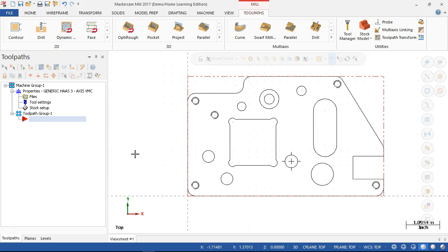If we're okay with the raw stock, understanding that it may have waves in it, may have scratches, scores, dents, dings, and otherwise as imperfections in the face, basically that facing operation is just to get this clean, make a nice, smooth, shiny surface. There are times where for cost, I may pick one side over the other.